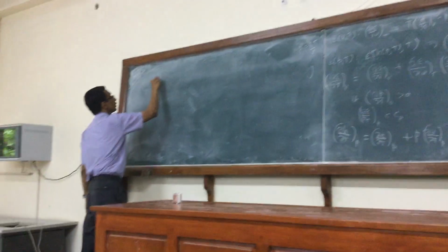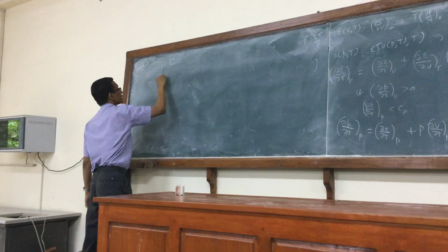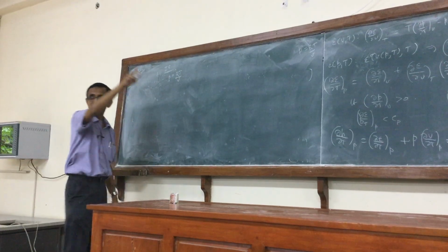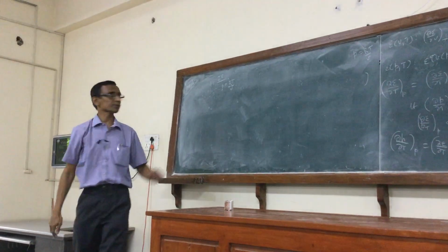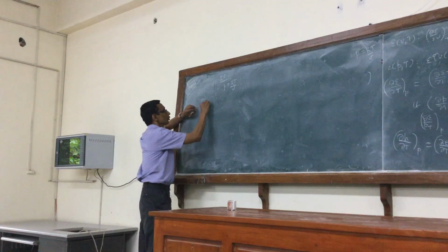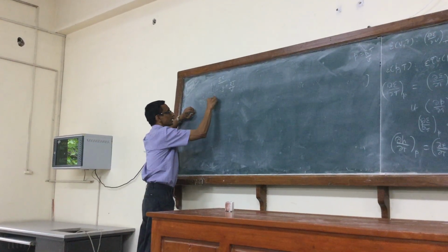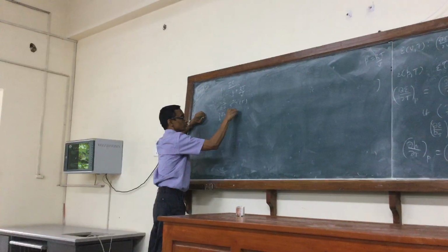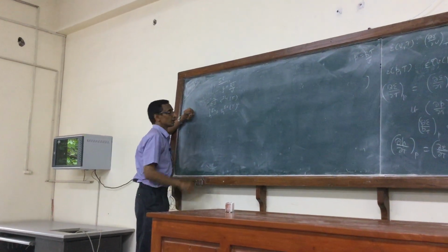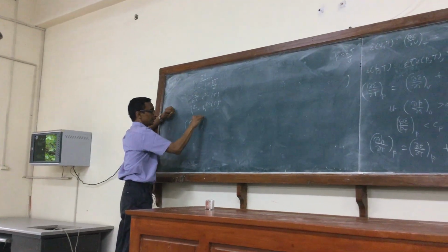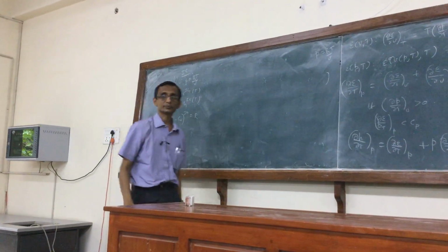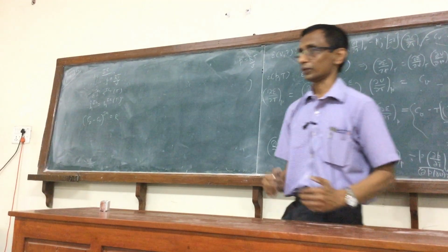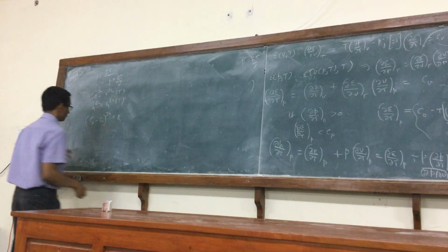So for the ideal gas, this is basically assumed. The rest of it follows from these relations. This is something that we assume. So say that E of the ideal gas is a function only of temperature. H of the ideal gas is a function only of temperature. Cp minus Cv for the ideal gas is R. Right? And what about S? That's an important property, right?